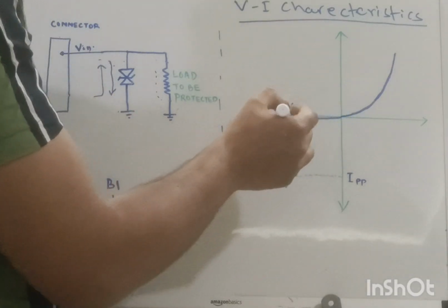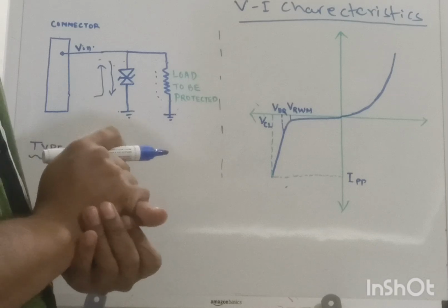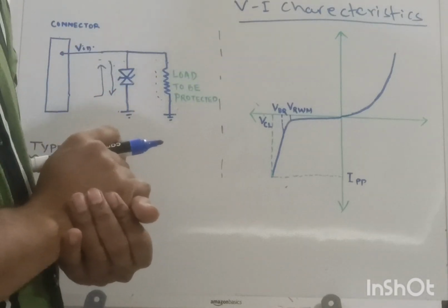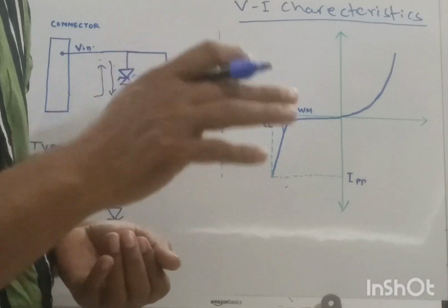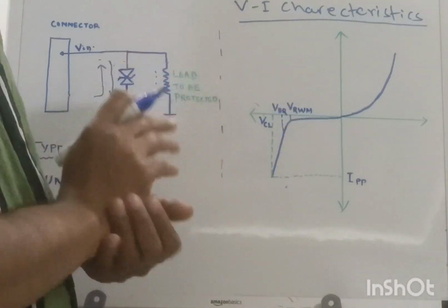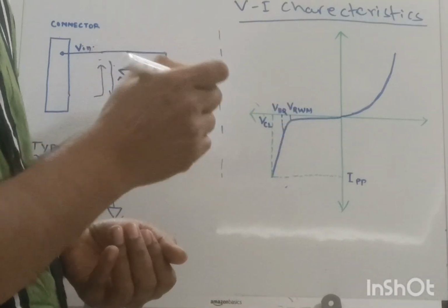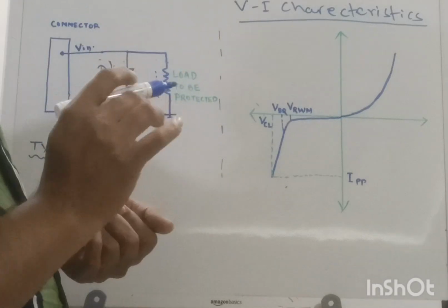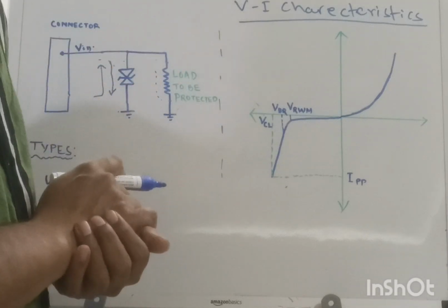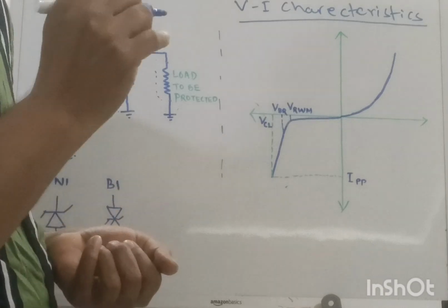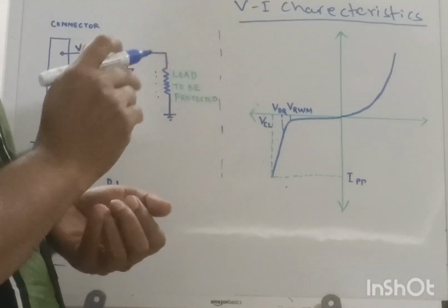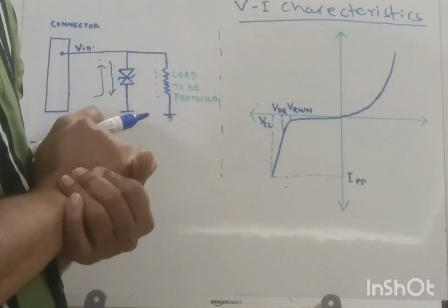To understand its operation, if you are selecting a TVS diode, you need to know the maximum operating voltage of your board. Once you know that, select a TVS diode that has VRWM the same as the maximum operating voltage of your board. VBR is your breakdown voltage, the voltage at which your junction breaks and current just starts to conduct. I mean, your TVS diode starts to conduct.